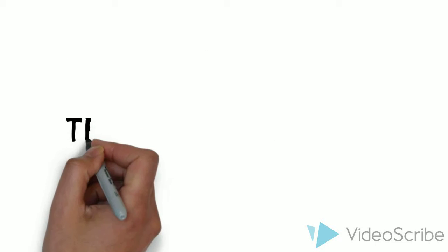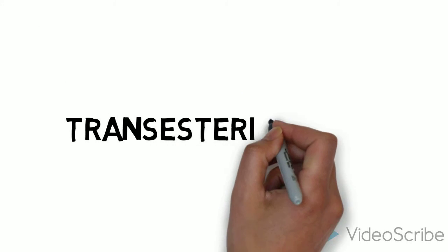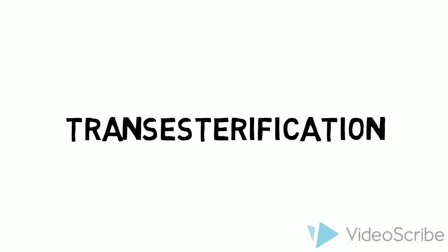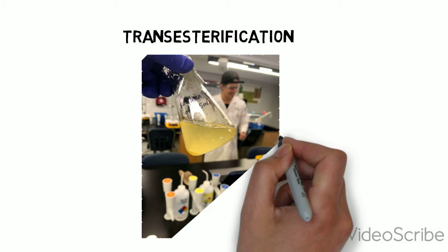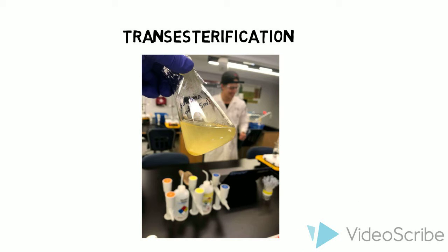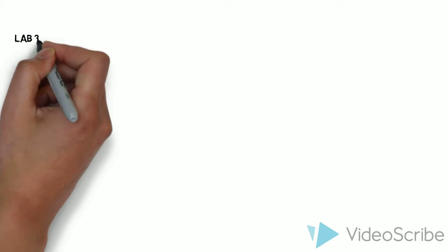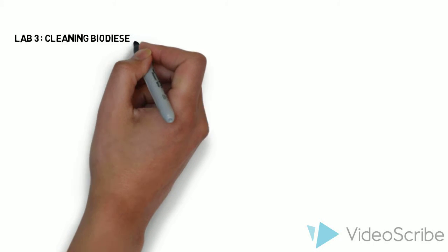In the transesterification lab, we produced biodiesel from both the oils through a transesterification reaction. The reaction will provide methyl esters and glycerol. The glycerol, which is not needed, will be cleaned out in the next laboratory, from byproducts and creating an acceptable and usable fuel.